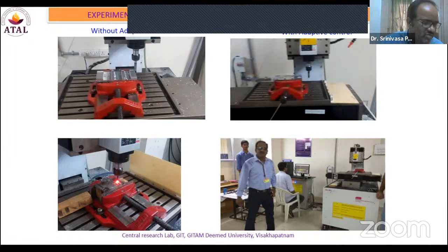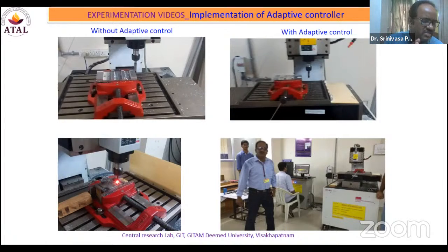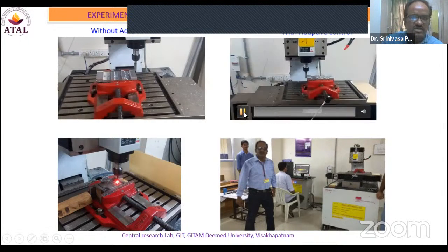When no vibration is identified, there is no need to continue with the same input parameters. You can increase the feed rate. It can be 2 times or 3 times. That particular decision was made automatically, and that information is shared with the controller of the CNC machine with the help of vibration identification. So for your sake, I'm going to switch on the video again.